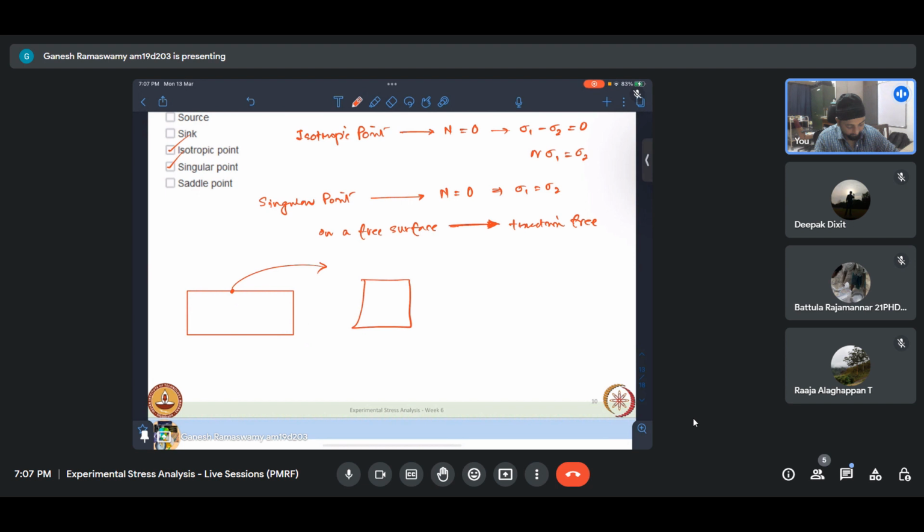I know that on this top element, sigma n and this thing cannot exist. This is what I know at that point, because shear cannot cross a free boundary. Let me populate it like this first. This is the most general representation of the stress element. Now, if the top surface is free, this implies that this cannot exist.